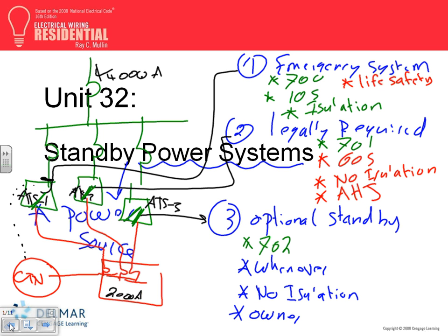So then what were you saying about the fact that it could have possibly backfed the system? What happened is, if you don't have an auto transfer switch, and you decided, I have an example here, guys. You decided to go bring your generator here. A lot of people bring a portable generator and plug it into the outlet. Completely legal. Bring a portable generator, plug it into one outlet. Now, from one outlet, you energize, and they come to the main here. They shut the main down. Now you isolate yourself from the utility.